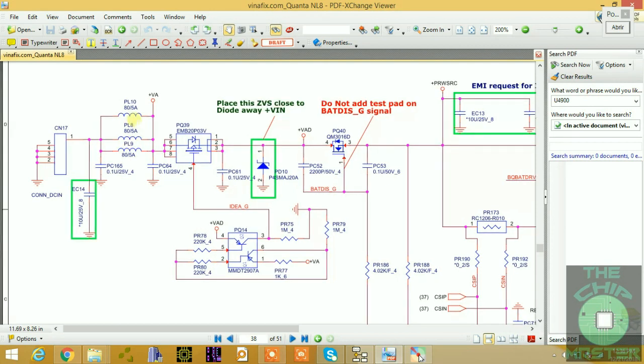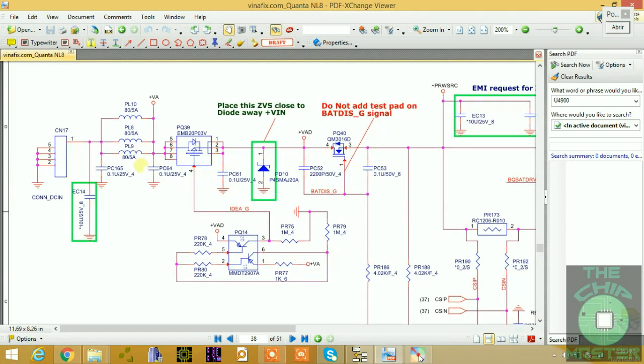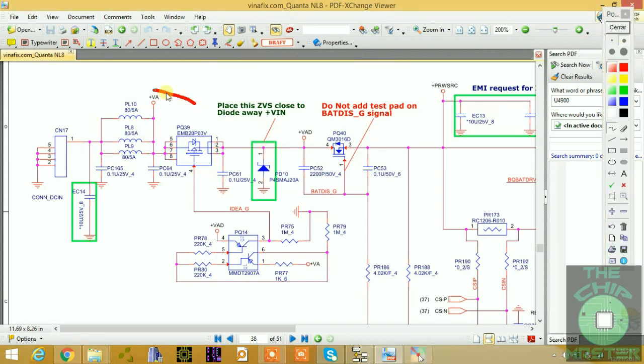Remember I said in the last class that these are your EMI coils, because as I said before, you have other devices giving off a certain amount of frequency when you're using your notebook, right? This is from your television, your cell phone, your radio, etc. And these always tend to interfere with the power supply of the adapter. So these coils with this Zener diode, as you can see, are used to protect. So this is your protection and isolation circuit, as you can see.